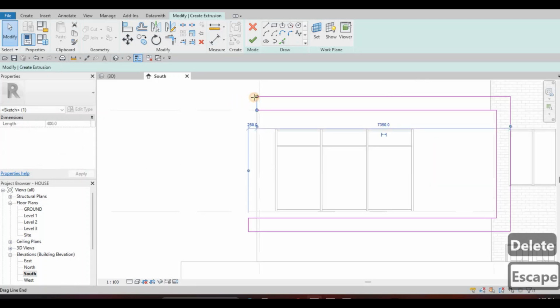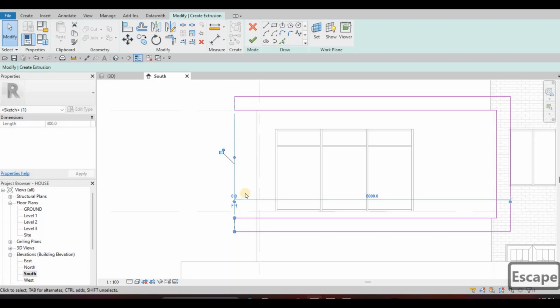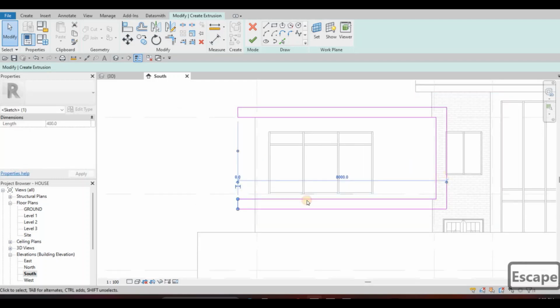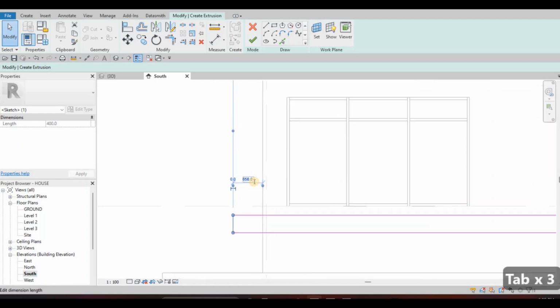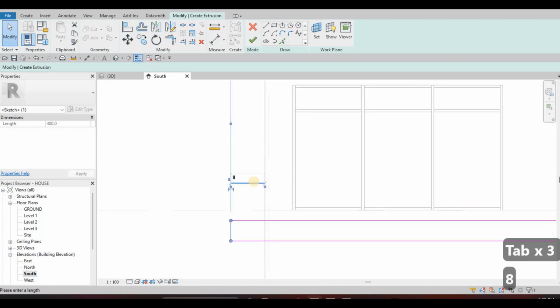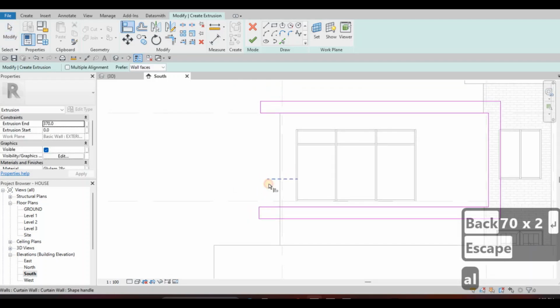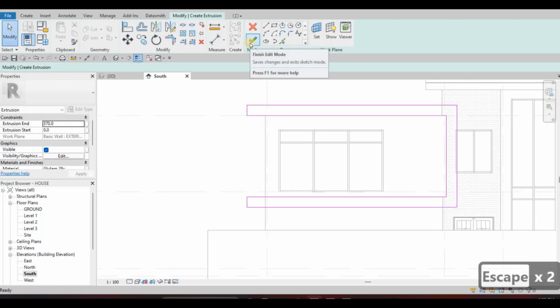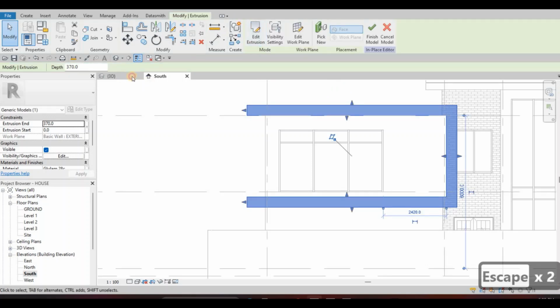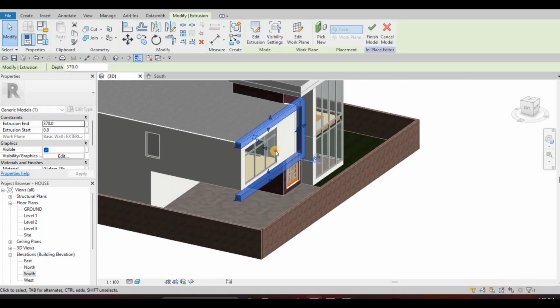Of course, we're going to extend this one a little bit to have our design to make it nicer. So I'm just going to extend this one around 800 or around 700, and then align it at the top. AL, at the top like that. So click on finish, and then I want to see it in 3D, and then we're going to expand it.